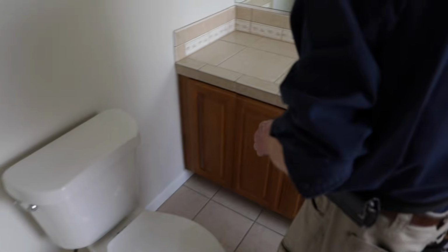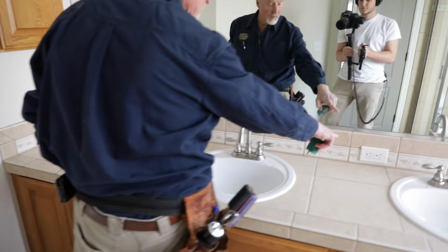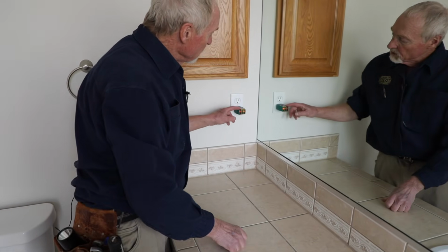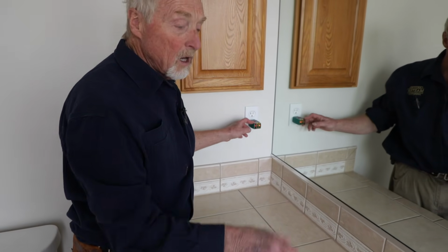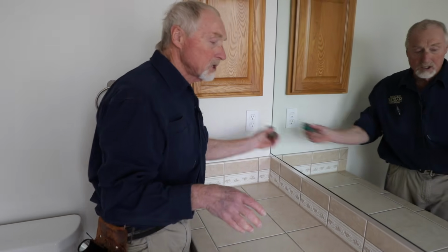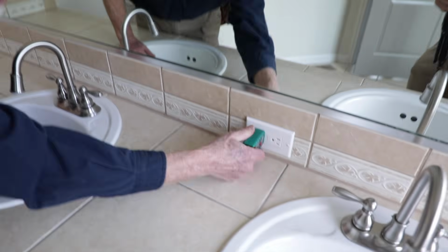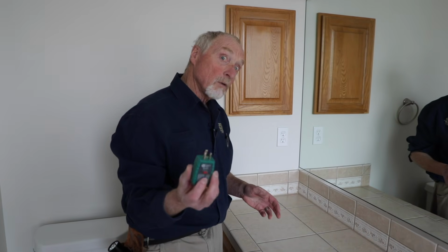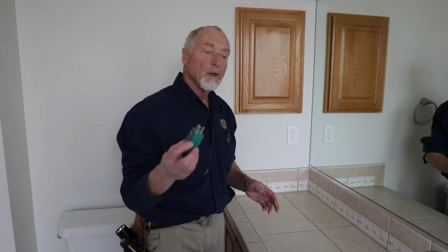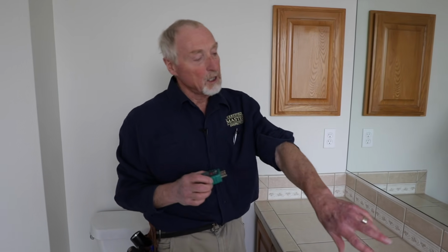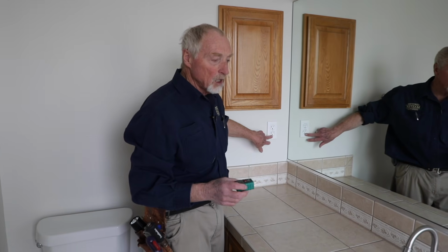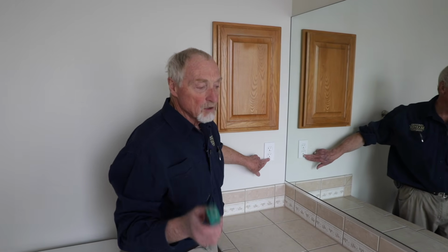Looks good. Take a look at my sink here. We have a GFCI here, which again is part of the electrical, but I'm here, so I'm going to be checking it. This GFCI may be controlling our basement. So it's probably controlling our basement bath also. And since I tripped it remotely from the basement bath, it's tripped here. Dead there, showing hot neutral reverse here, which is an indication it's wired incorrectly.